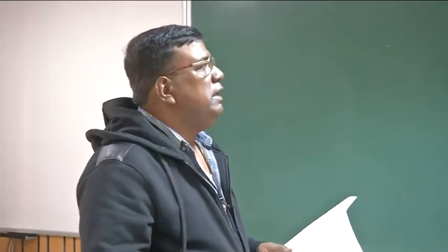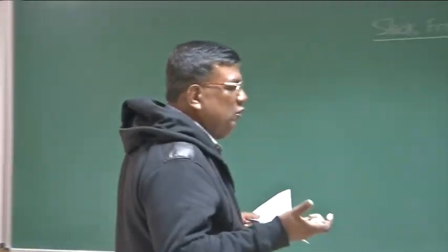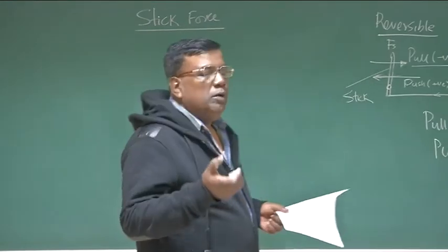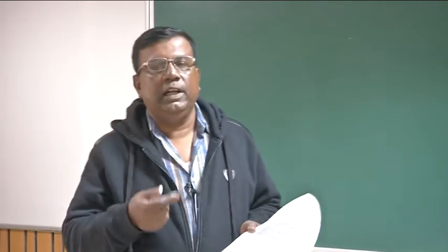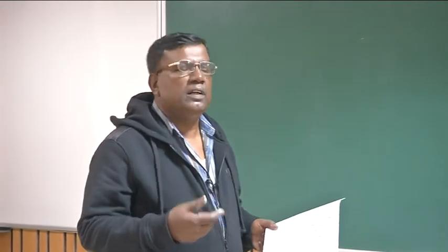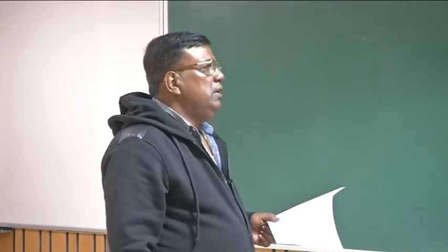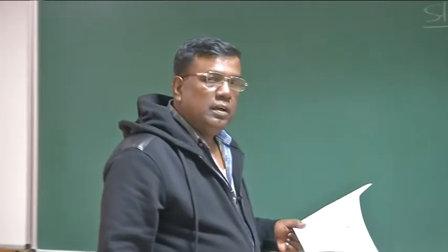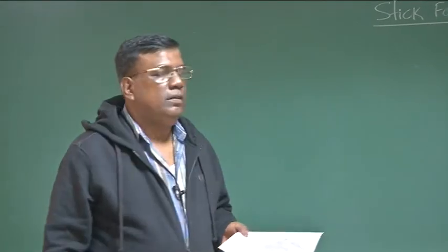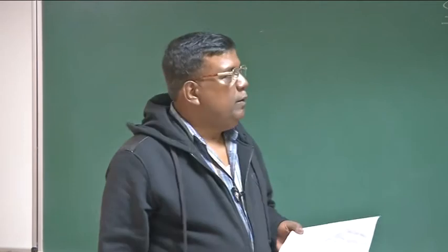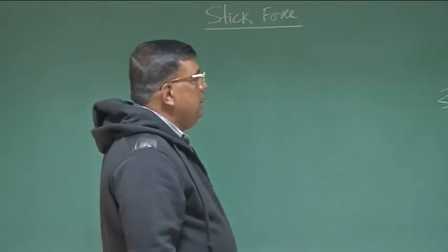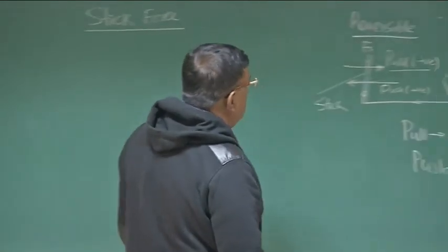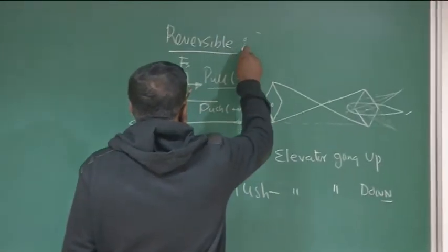But in irreversible control, which most aircraft have, there are boosters and actuators, and that sort of direct reversible relationship is not there. So the stick force relationship will not hold true strictly, and one may ask what the relevance is. But we will do this, as there are important things to learn. So this is what we are talking about: a reversible control.